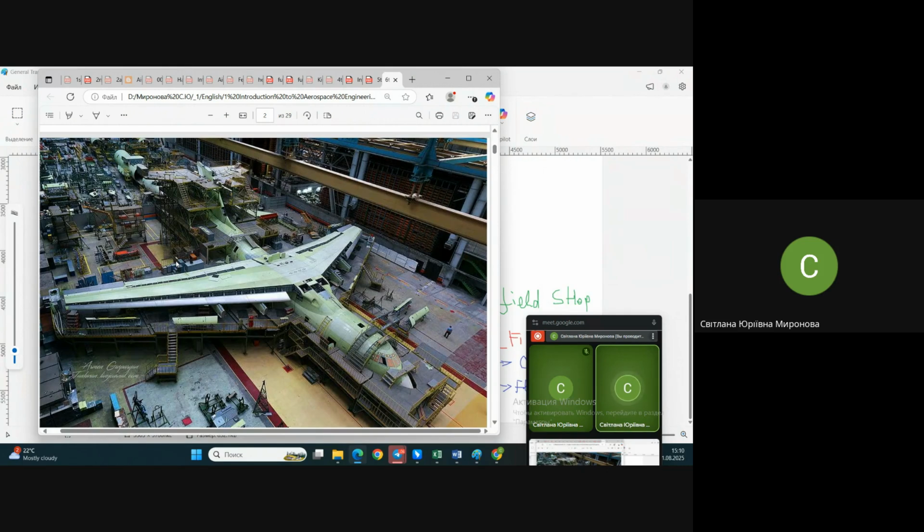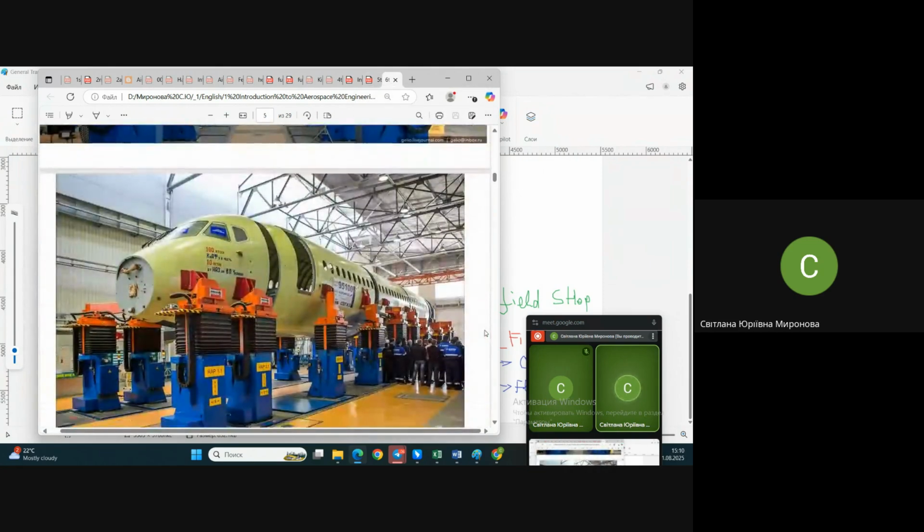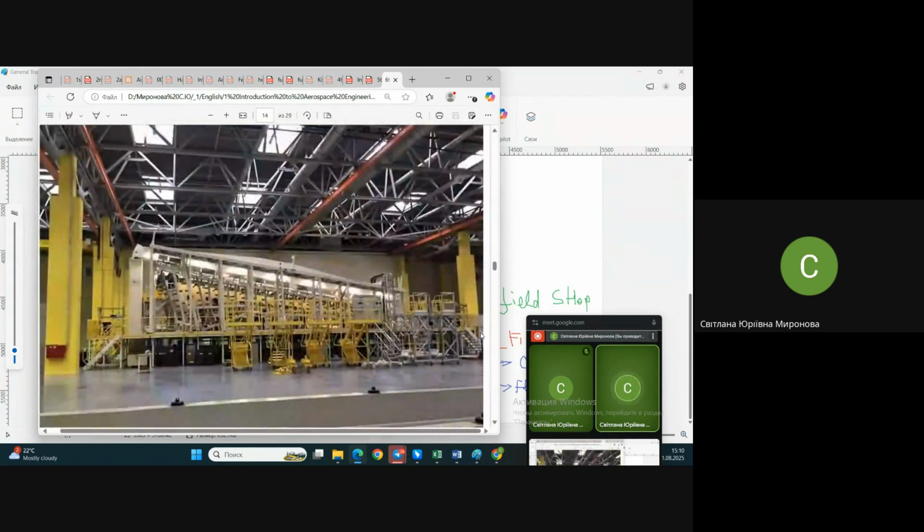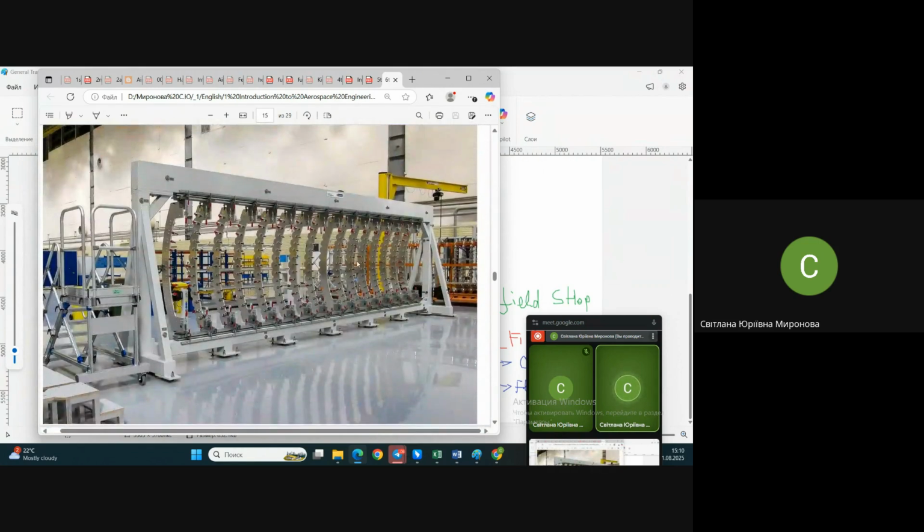Next, how to provide coordination not only between them during assembling of the assembly jig, but also, you do remember, we have beforehand, we need to produce panels, for instance, in a panel jig, and it means that the panels jig should be coordinated with panels for the fuselage. Jigs should be coordinated with the jig of the fuselage compartment or aggregate at all. And moreover, they should be coordinated with the punches for manufacture. They should all give the same results.